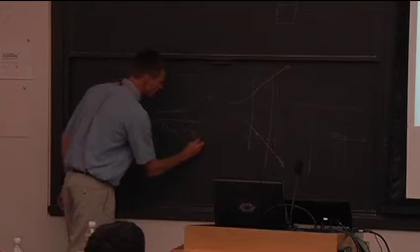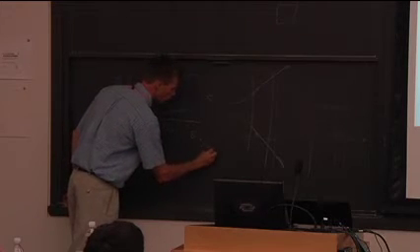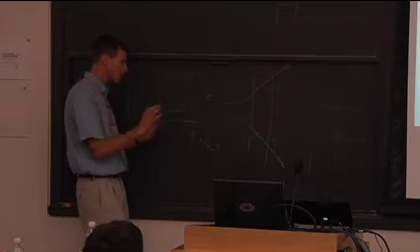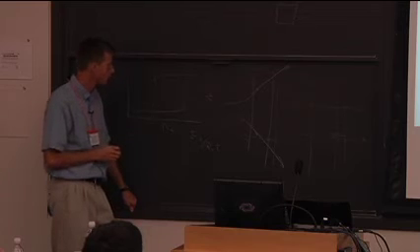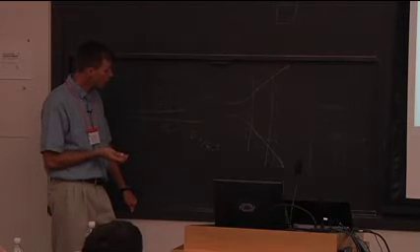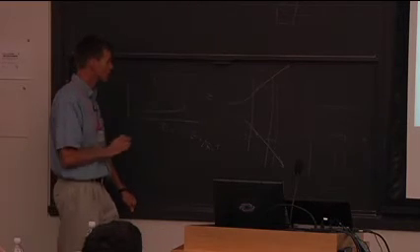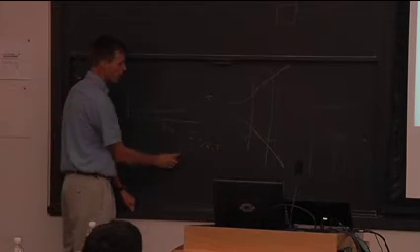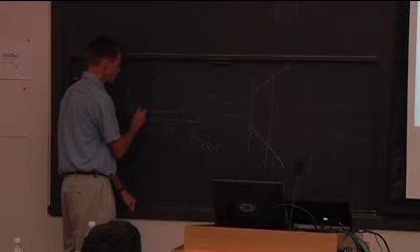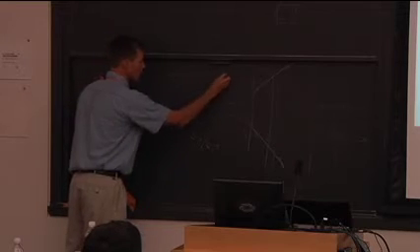It's E sub A over RT. And again, this is single-step kinetics. Real flames don't have single-step kinetics, but we'll just run with this for a minute. Well, there's two ways that you can not have it. As soon as you lose high activation energy, the S-curve goes away, right? So if the high activation energy is not high, you'll get something that looks more like that.